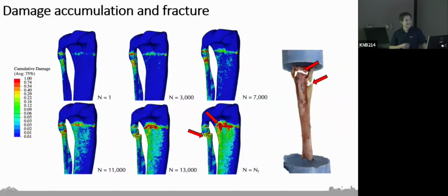Brent, can you just clarify how long it takes to run one simulation to failure? Yeah, the optimization takes months. That's to get the constants. Now you have the constants. How long does it take to put in a new model and figure out when it's going to fail? Yeah, another good point. It really does depend on the fatigue life of that phone. If it has a higher fatigue life, or if we're loading more high cycle fatigue, it's going to take much longer. But if we're looking at, let's say, 12,000 loading cycles for the fatigue life, this would probably take about 2 hours to run.